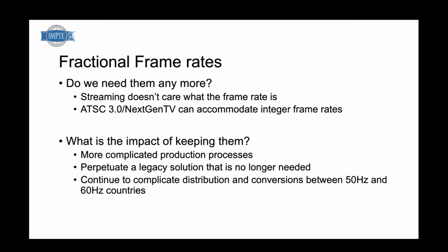Yeah, go ahead. So I'm looking at a SMPTE document called the UHD TV Ecosystem Study Group Report from March of 2014. The discussion then was, should we include 120 frames per second or 120? I remember that. 119.88, right? Let me read two paragraphs, I'll read it fast. It gives a great sense of why they decided they couldn't do that, and why they had to include the 120 over 1.001.